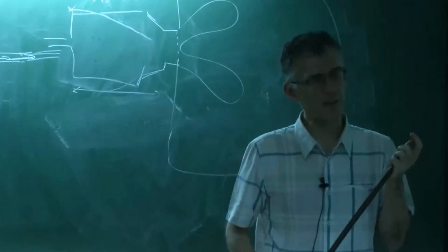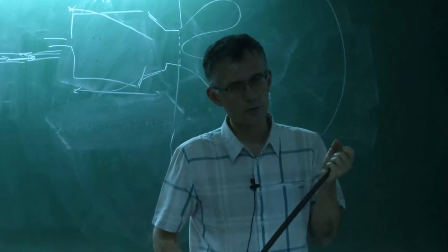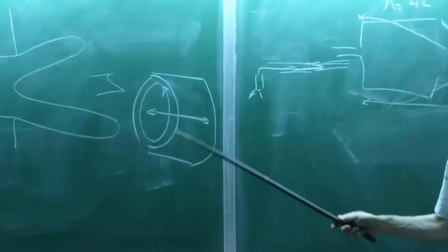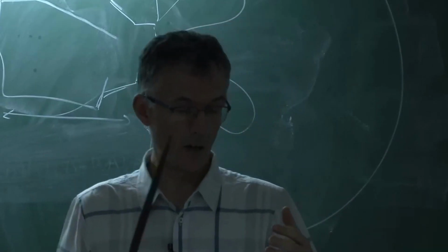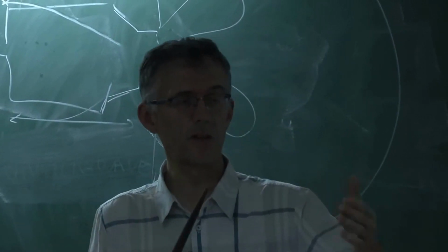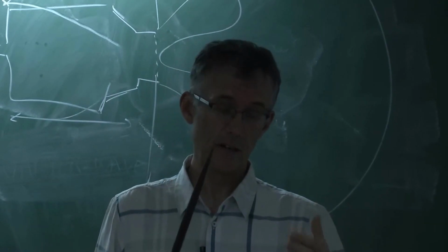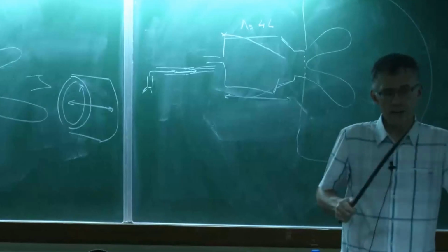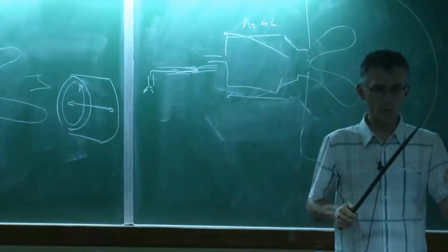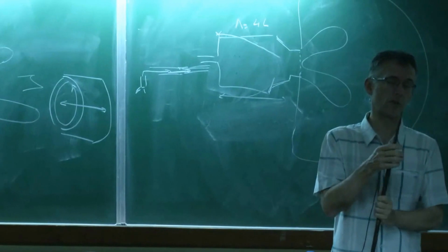The physical reason now, why does the flame choose a longitudinal mode instead of a transverse mode? This has to be related to the Rayleigh criterion again. You need certain phase conditions so that the flame locks on one mode or another. And this is what LES does, and the acoustic modes do too. You have to include the flame transfer function.